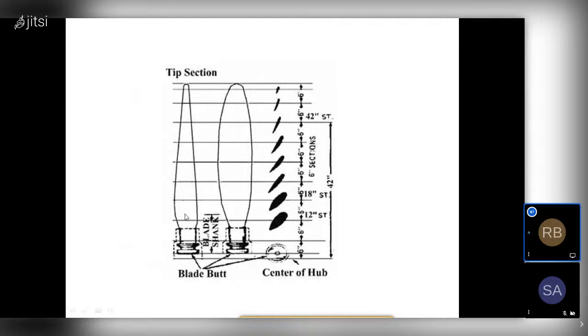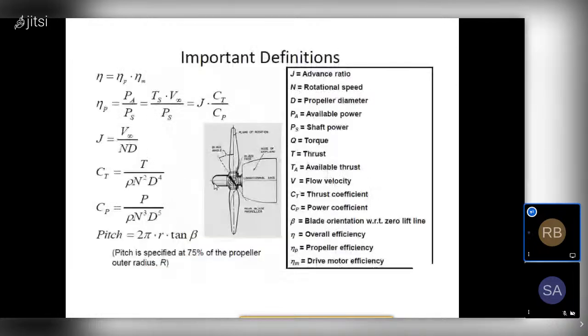The tip section of a propeller operating at greater than 0.7 Mach should be designed to operate at small CL, that is less than 0.5. And with respect to density, the propeller efficiency even affects the size and shape of the complete design parameters.